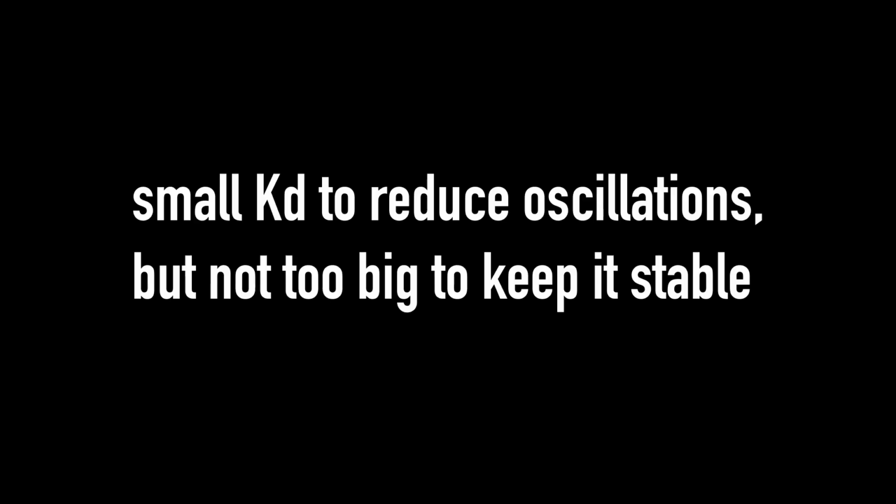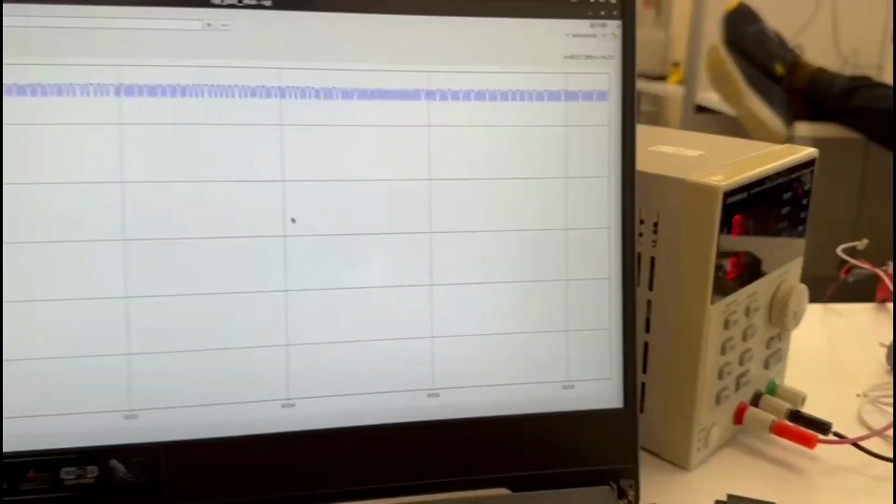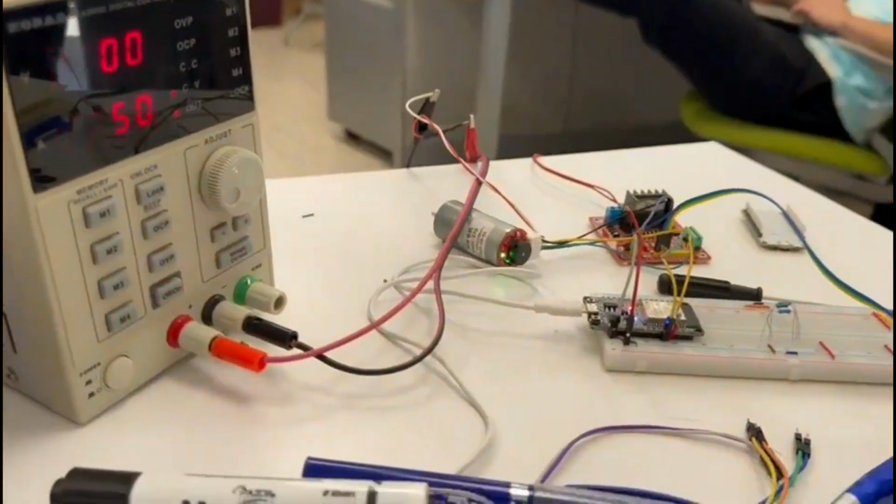When it came to tuning parameters, we went with a simple and manual approach. In this occasion, there was no need to get theoretical. We first started with our KP. We noticed that a big one would cause vibration, so we chose something low. We then proceeded to see a steady state error, which we diminished with the KI parameter. Finally, the KD parameter remained really low, just enough to diminish the oscillations, although there were some negligible ones due to the way we were measuring the velocity and the quantity of the steps in the encoder.